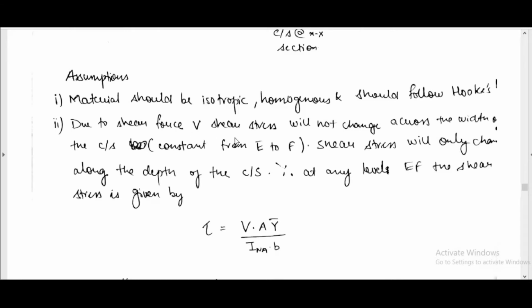shear force V versus shear stress: due to shear force variation, the shear stress will not change across the width. The cross section is constant from E to F. Shear stress will only change along the depth of the cross section, y, along the depth of the cross section.